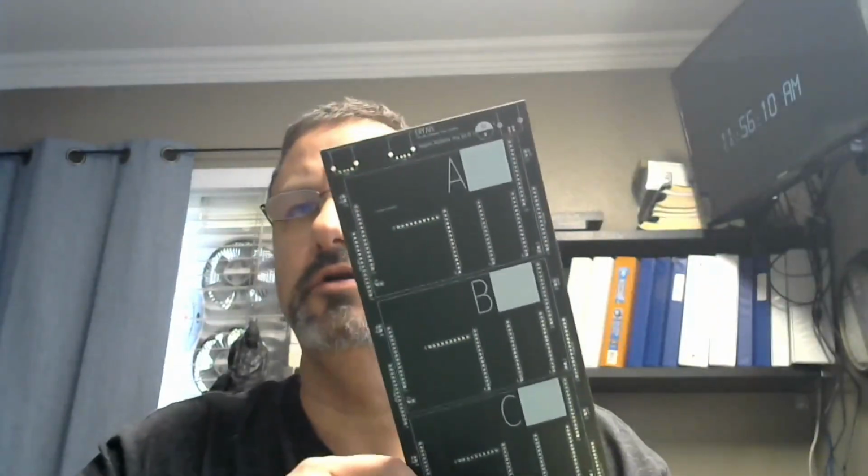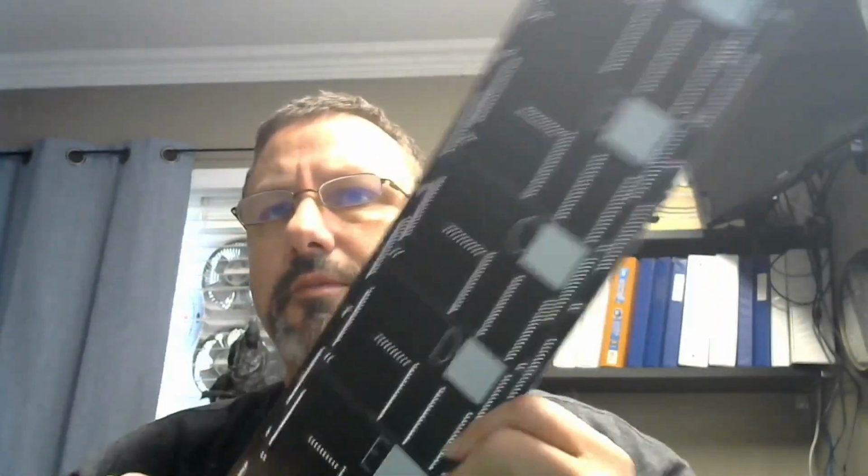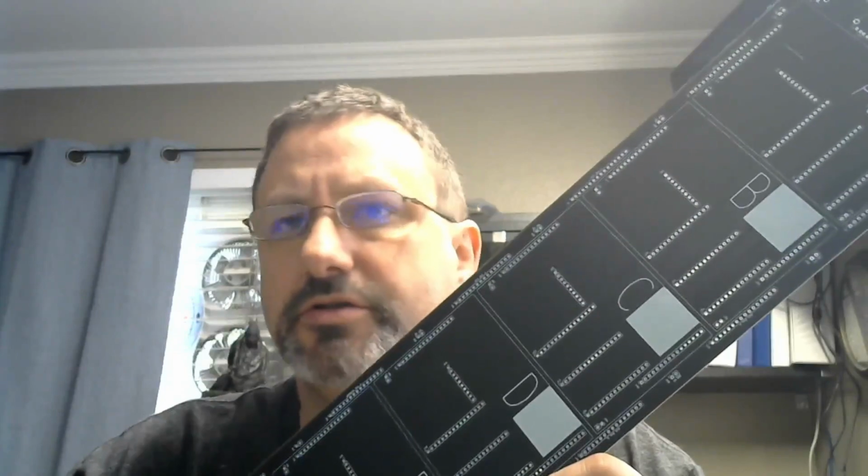I also need to take and expand from an 8-bit instruction to a 12-bit instruction and clean up the issues that results in related to the main bus assert. So there's going to be some pretty hefty changes related to this that come up in the next few videos. The very next video, on the other hand, is going to be soldering up the backplane for my registers.